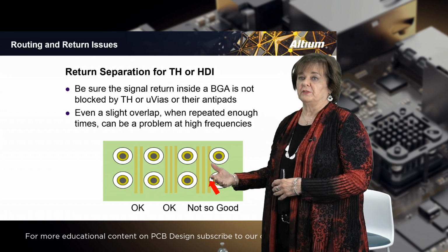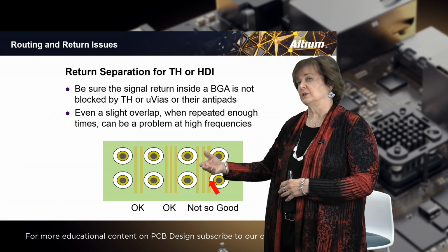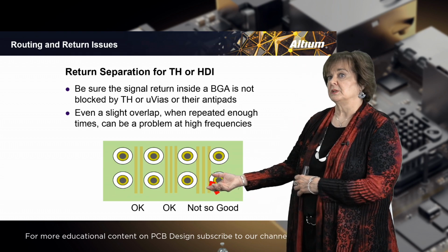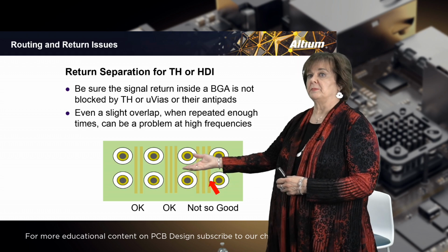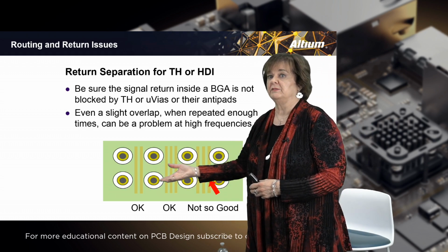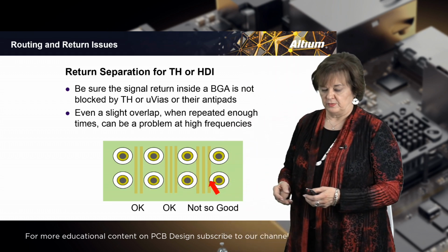Even the slightest bit of overlap done enough times can cause common mode noise, which can cause EMI problems or noise on your board problems. And so we want to try to set up everything to where it's evenly spaced and not overlapping even the anti-pads of those parts.